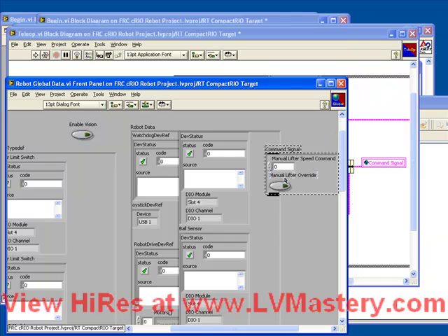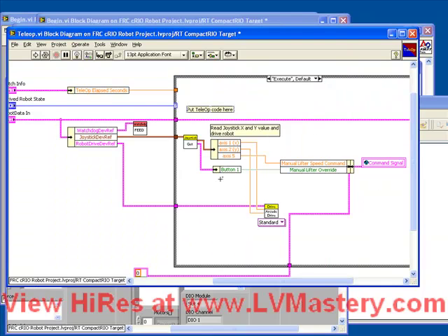They could be other speed commands, they could be other override commands, they could be any other information. But the key thing to remember is that only the Tele-Op can write to the command signal. So every time Tele-Op runs, it's going to read not just axis 1, 2 and do an arcade drive, but it's also going to put button 1 and axis 5 into this global.